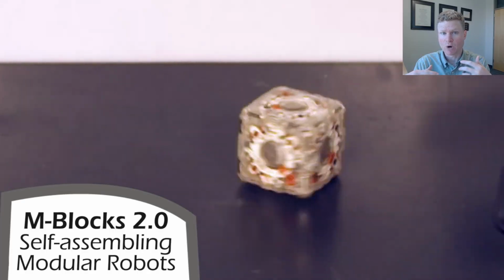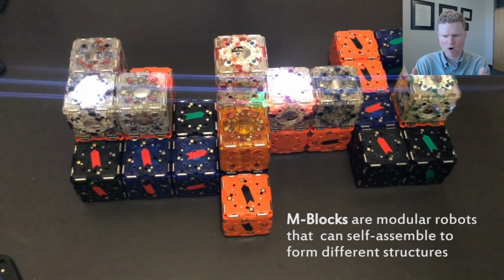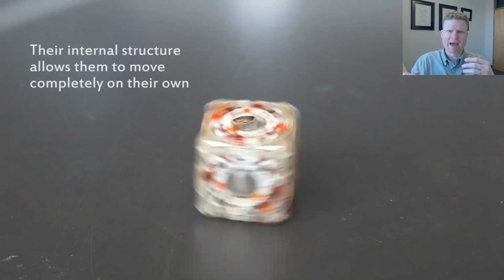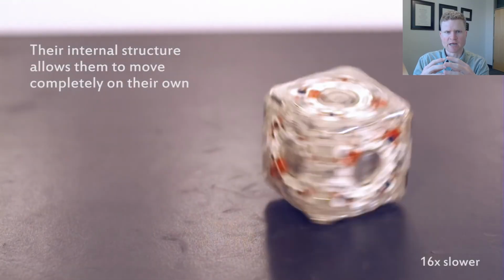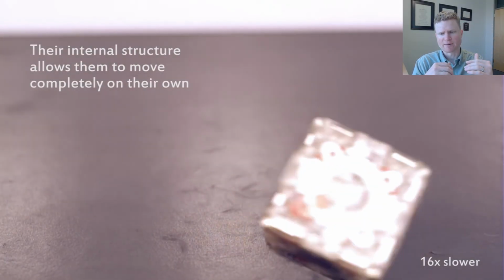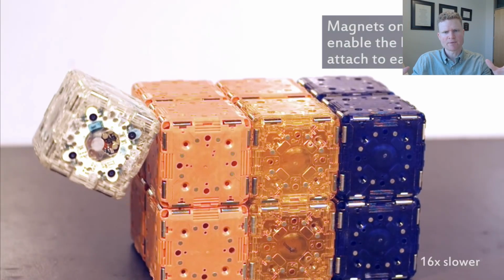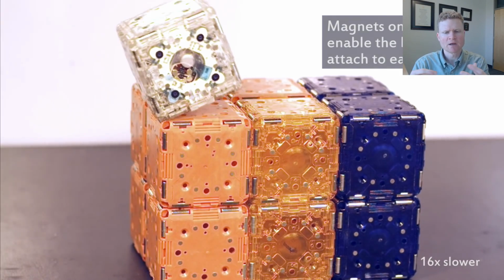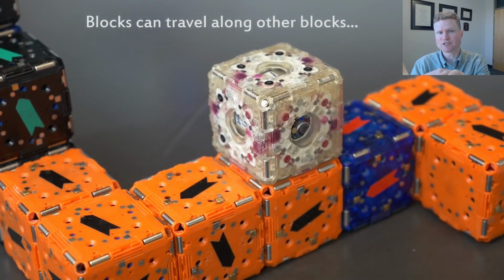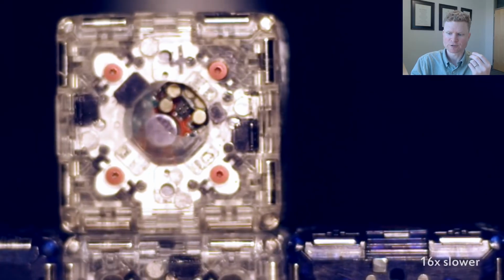Now, this is a video of modular robots. Modular robots are small robots that can self-assemble into larger structures. Maybe you could imagine a fleet of these modules coming together to build a bridge. Modular robots present a motion planning problem at multiple levels. At a high level, I'm thinking about my overall shape and what sort of shape I want to build in order to do some meaningful task. At a lower level, I need to plan the motions of each individual block, making sure those blocks come together to assemble this larger structure.